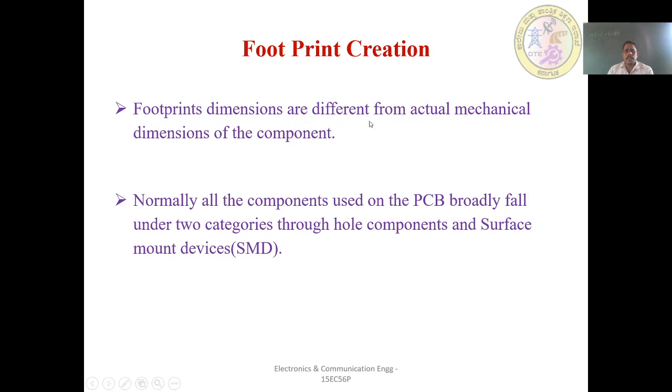Footprint dimensions are different from the actual mechanical dimensions of the component. The footprint dimension is always more than the actual mechanical dimension of the component in order to fit into the PCB, which should not create any problem to the nearby component.